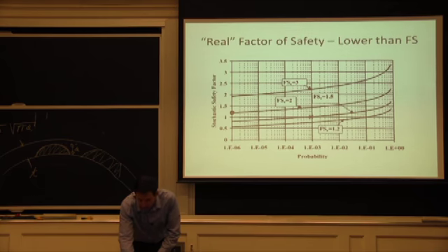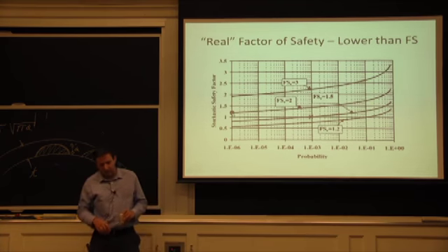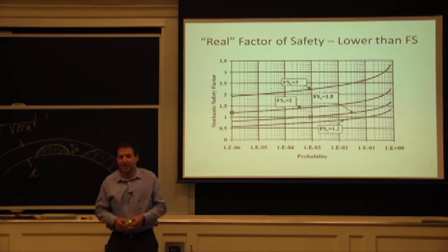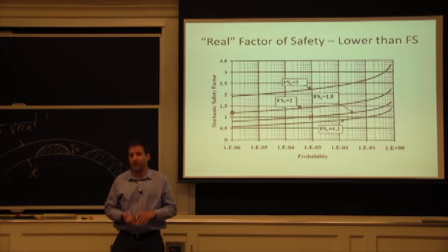And I specifically picked the factor of 2 as the initial safety factor. This is what they call a stochastic safety factor. So the real factor of safety comes down to about 1.2. So that's taking into account probably some maintenance, some inspections, some variation in loads that were not expected.